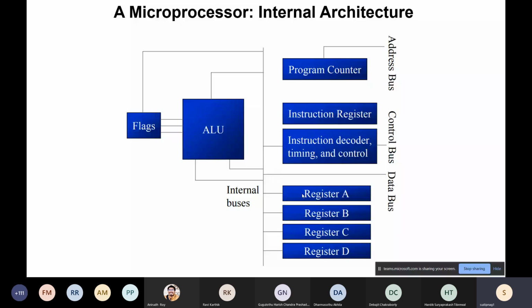Now, after these two things came, the first data came to the instruction register, and the second data came to A. Data means from the program space. For the microcontroller or processor, it is just a value, and based on the value, we are making some decisions. Based on the first value, after decoding, it decided that you need the second data. It incremented the program counter, PC, and then got the second data into the register.